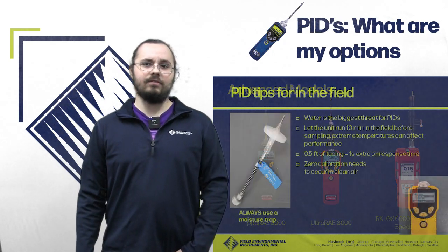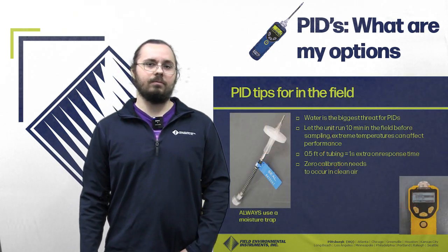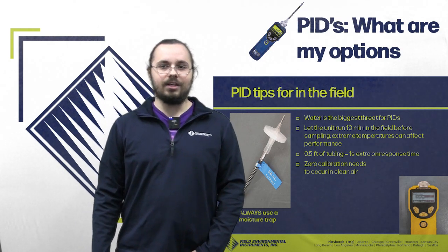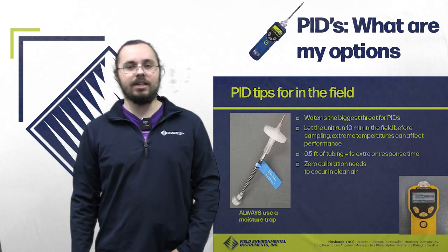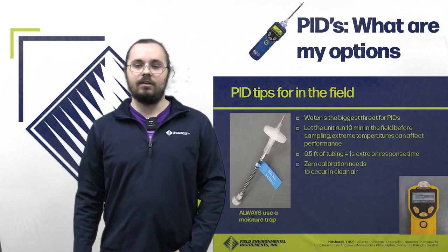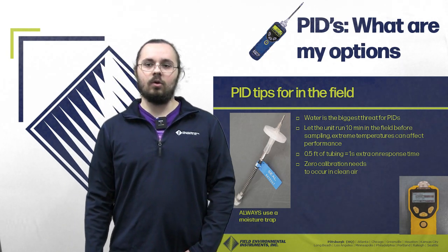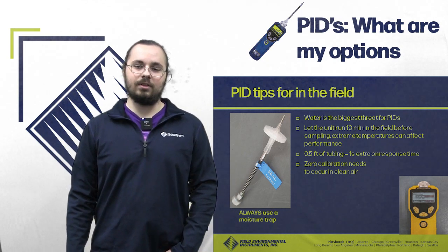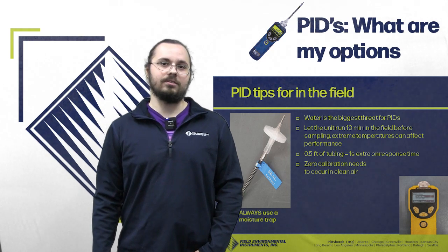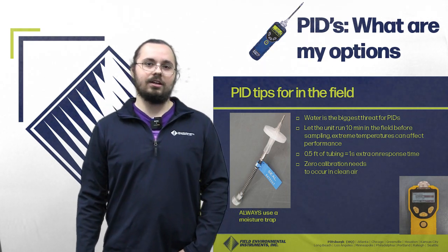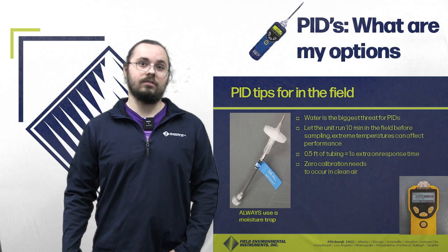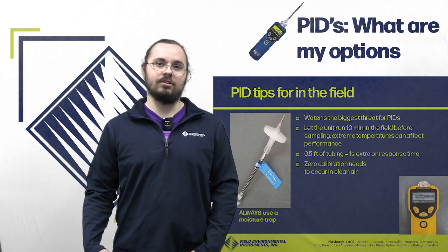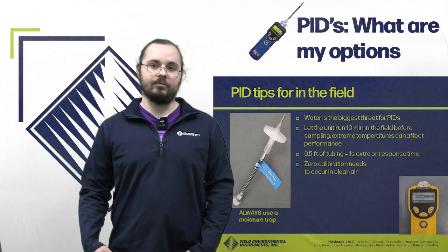Lastly, I just want to give you guys a few tips for using your PIDs out in the field, as it can be a little finicky sometimes. As I've mentioned before, water is the biggest threat for these units. The best way to combat this is to always use a water trap, which you can see in the picture there: the little plastic piece with a little metal piece on the end. This essentially allows it to absorb any small traces of water before it gets to the actual PID sensor, which can cause damage to it.